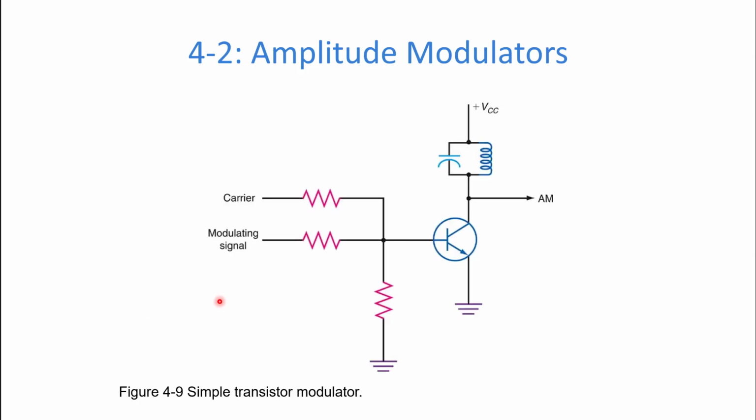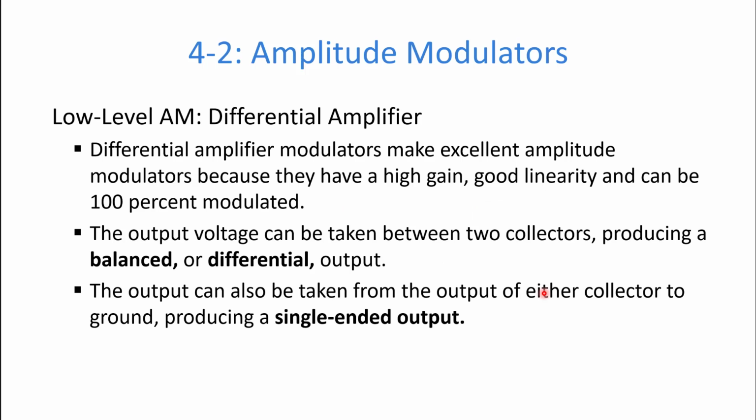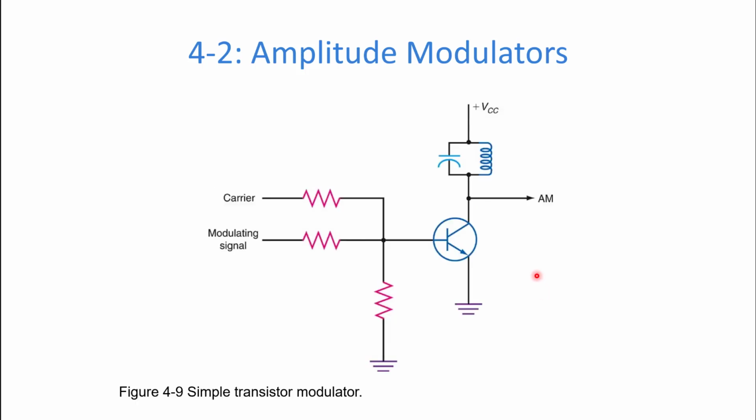And this is what it looks like, right? Notice that we use a BJT because we're kind of making the reference back to the diode, but this can be other types like FET transistors, for example, right? You can still do that, right? And this would be your AM signal. Notice that in this one we show part of the bias, right? There might be some other biasing for the base and stuff that we're actually not showing.